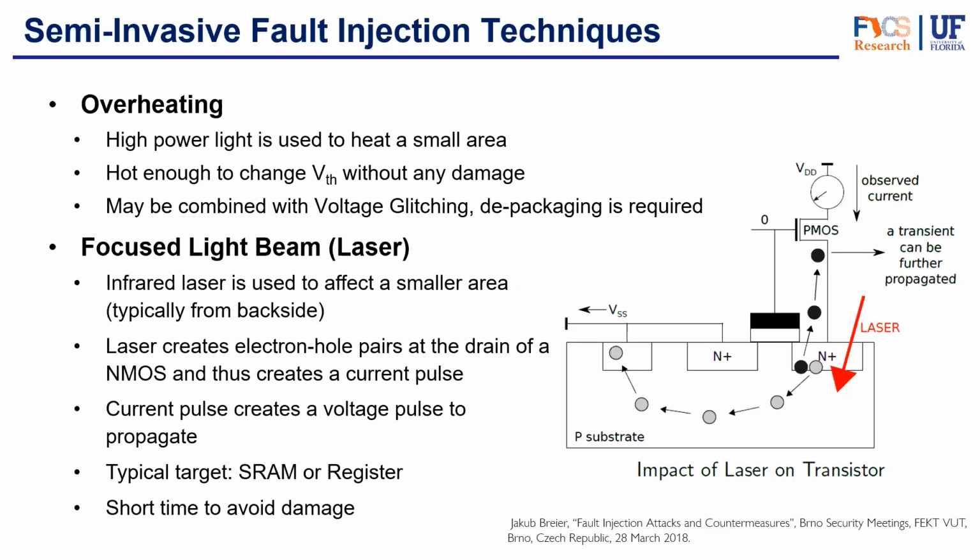There are some successful attacks shown in academia that, by changing only one bit of the key in AES applications based on differential fault analysis, that particular bit of the key can be leaked by faulty operation of the design. Comparing the correct operation of the design with the faulty one, differential analysis can reveal that one bit of the key, and that can be repeated to extract a major part of the key.